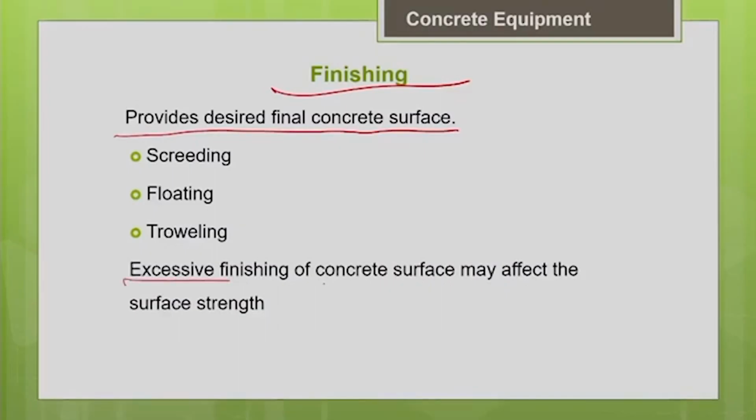That is really a wrong practice. We should never add water to manipulate the surface to get the desired texture. Never do excessive finishing of concrete. Only the minimum finishing needed to get your desired texture should be done, because it will harm the concrete.